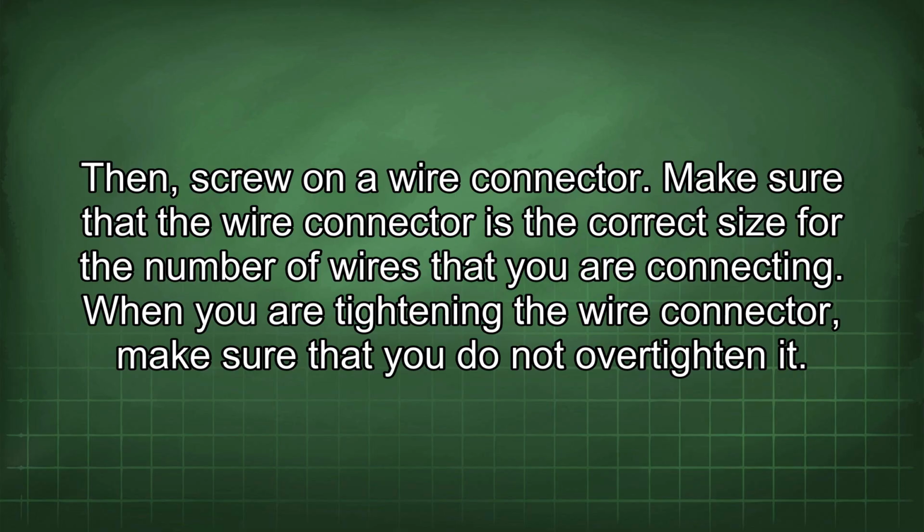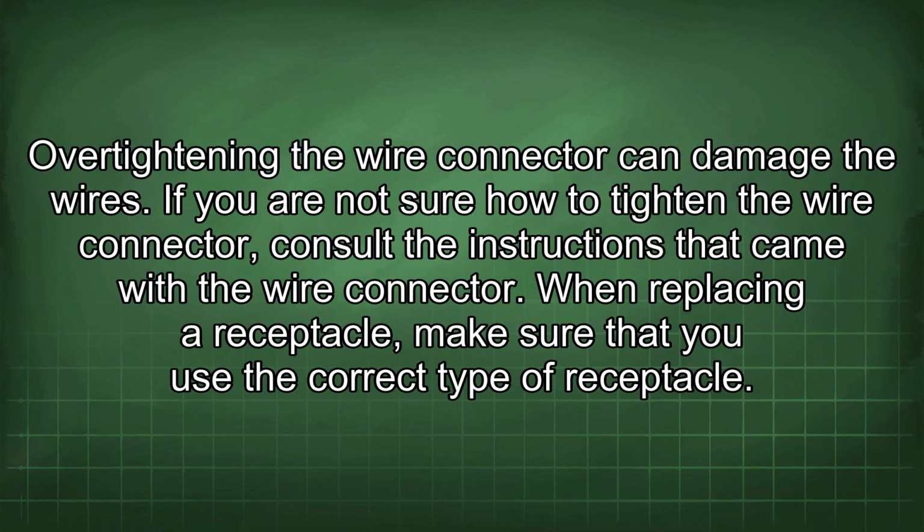Make sure that the wire connector is the correct size for the number of wires that you are connecting. When you are tightening the wire connector, make sure that you do not over-tighten it. Over-tightening the wire connector can damage the wires. If you are not sure how to tighten the wire connector, consult the instructions that came with the wire connector.